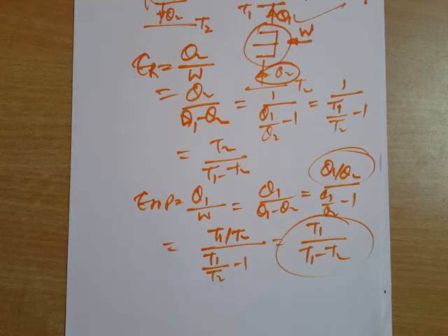So friends, before winding up this lecture, I will once again focus on irreversibility. So how many types of irreversibilities are there? Basically, 2 types. First one is internal irreversibility and second one is external irreversibility. What is internal irreversibility? Internal irreversibility means the irreversibility which comes into the picture because of friction and internal dissipative effects. And what is external irreversibility? That which occurs at the boundary of a system, because of boundary phenomena. And you know, heat transfer is a boundary phenomenon.